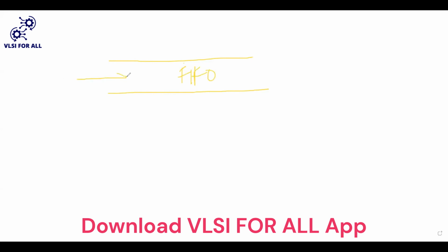I need to push some variables and I need to pop some variables. For pushing, let me consider I need to write them, and for popping, I need to read them. If for writing and reading there is a single clock, meaning the FIFO is working with reference to a single clock, we are going to call that a synchronous FIFO, because everything is synchronized to a single clock. But the asynchronous FIFO is if there are different clocks for the write and